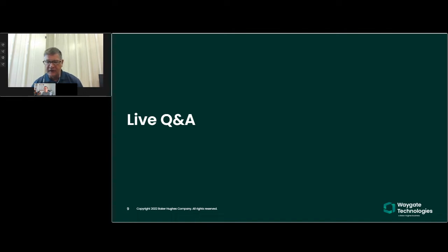Let's see. How do we save files on the D drive? I was having trouble the other day. So when you're trying to save files, at least on the Mentor Visual IQ, you would go into File Manager and you can choose where to save your files. You can save them on the internal drive, or you could save them on a USB drive. If it's USB, you have to make sure that you have a thumb drive plugged in. If you're still having issues, that's pretty simple to do, so I'm assuming you may be having an issue there perhaps.